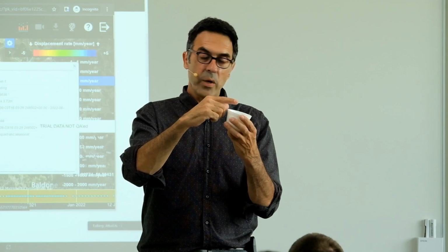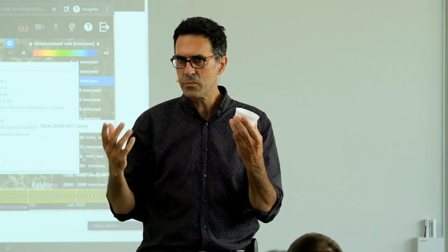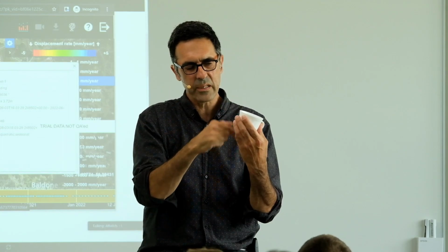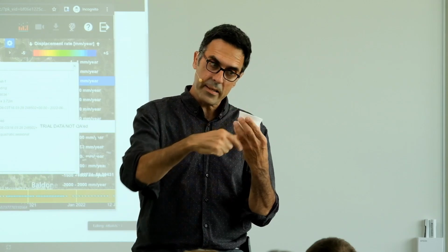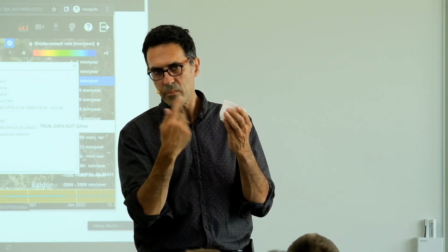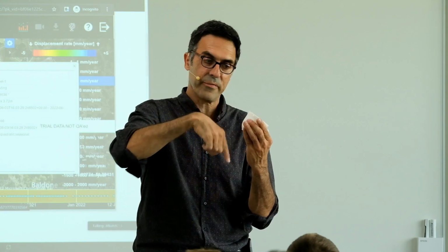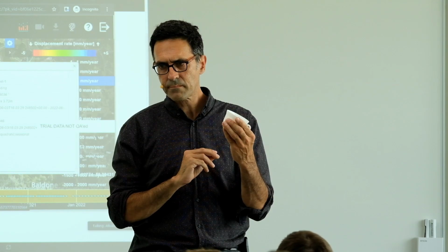And you can design it in such a way that if that is the sun, and you're flying in this plane, the solar panels will always get solar illumination. A radar is a very powerful instrument and needs a lot of power. So you need the solar panels maximally; it will always be a little bit in an eclipse, but you want maximum solar power. Then you can also design the orbit in such a way that, let's say every 12 days, the Earth has made an integer number of revolutions, and the satellite has made an integer number of revolutions around the Earth, so you're exactly at the same spot.